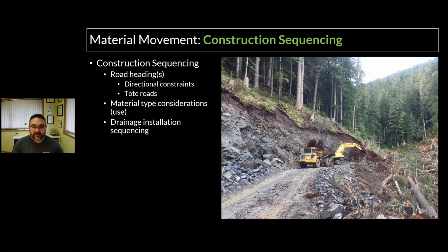And again, in the same way, if you are going to be staging those things, stage them in a way where if there's useful material that you are going to use later, you're putting that aside into a place where you can still access it. And again, as you get bigger on spoil sites or borrow sites, you might be digging into more detailed design. In that previous slide, that spoil site actually deserved and got a slope stability analysis and a detailed design, because it really mattered where material was going to go. And there were several spoil sites in that particular example where you could move different materials so that you could build them in the way that you want.